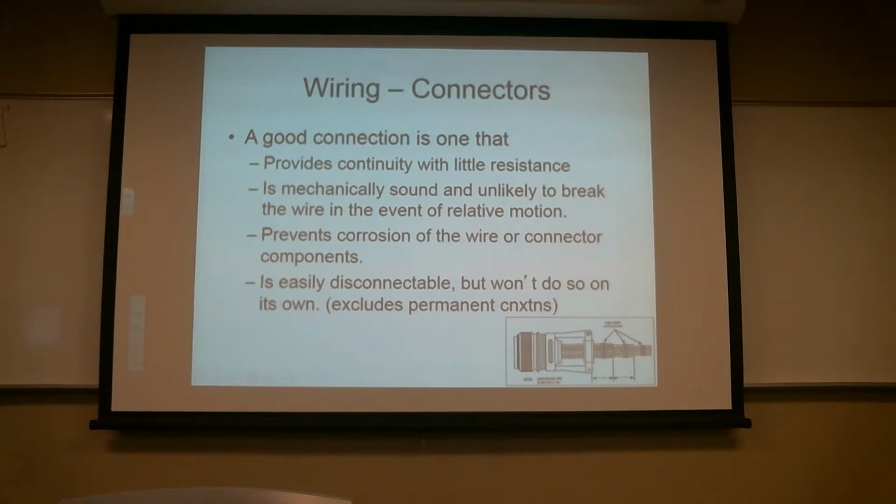And so the players in aviation realize they've got expectations. Because the last thing in the world they need to find out is that John Q or Jane Q mechanic connected and disconnected a few times, and it was such a bad connector that the process of connecting and disconnecting caused the wires to fail or the pins to fail, and at some point pin pushback happened and everybody died.